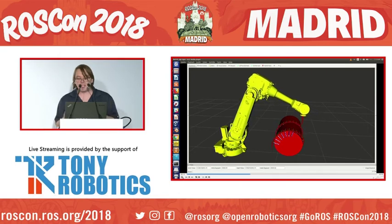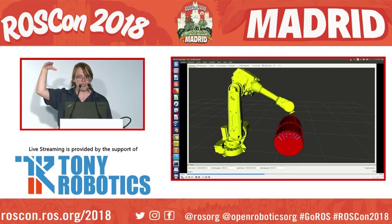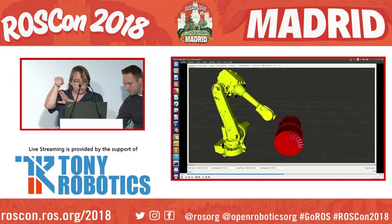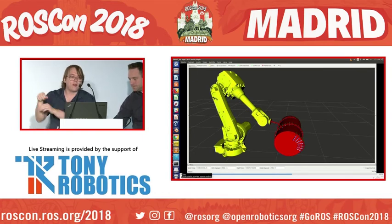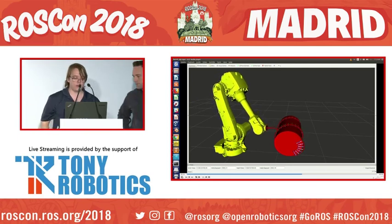And you can kind of imagine, there are all these points wrapping around the barrel, and the robot starts up in the air at 90 degrees. Some of the points are on top and some of the points are on bottom, so some of the robot poses go to the top and some of them go to the bottom, and it wraps around the barrel, and it can't quite handle it. It'll fail to plan. You can go ahead and let it finish. And you'll see the same behavior here again.